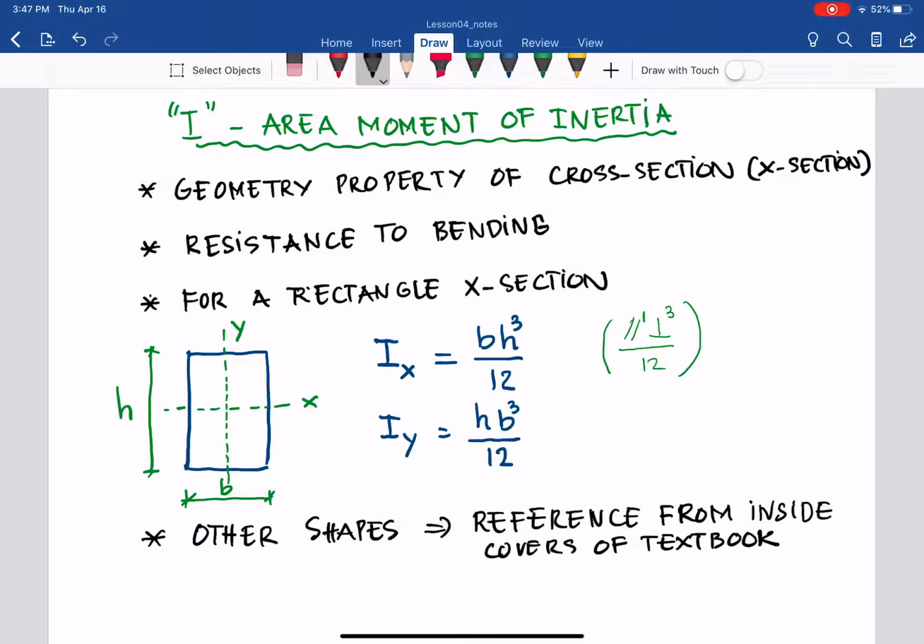Exactly the same. We make a table for area moment of inertia. Just change whatever the mass, the m, you just change to the area, the A, in that equation, in that table. Even the parallel axis theorem, we change the m with the A. Everything will be the same to determine the area moment of inertia.